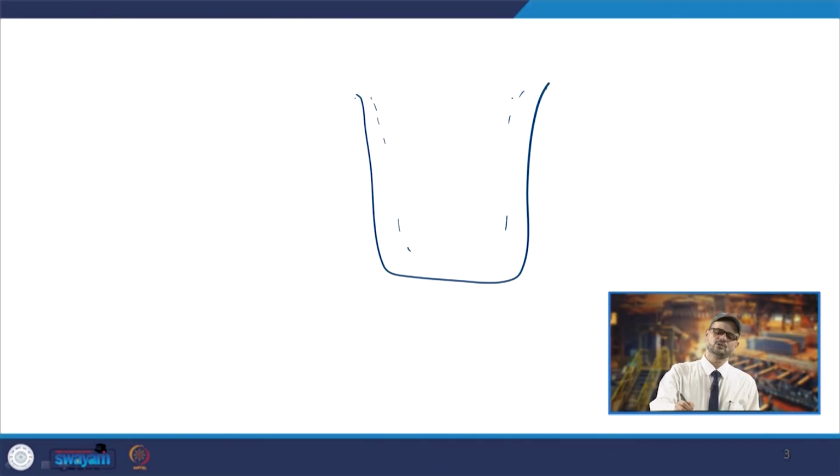Because of the very large sizes, you have different types of grain structures, not always preferred grain shapes, sizes and orientations too, and also you are likely to have centerline shrinkage, maybe also solute redistribution kind of defects. And there will be certain other kinds of casting defects.